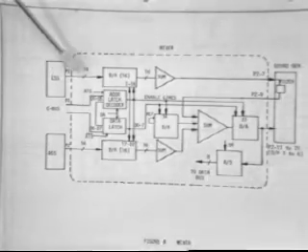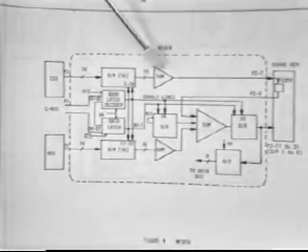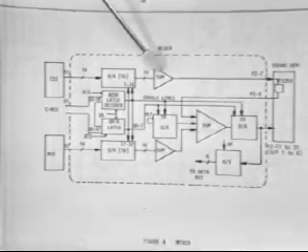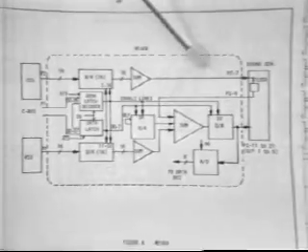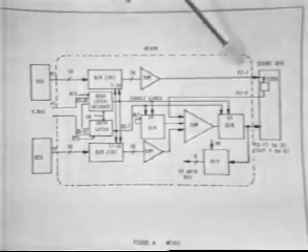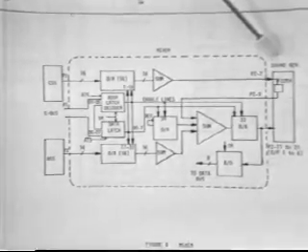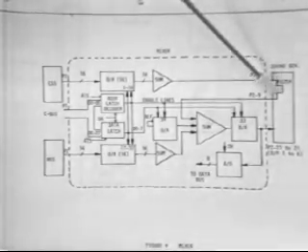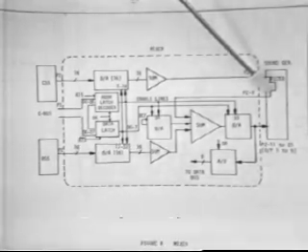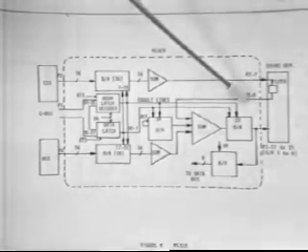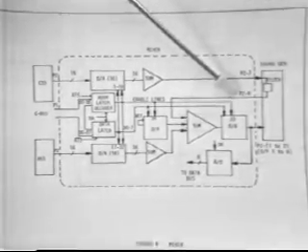Now, you'll notice that the CSS goes out through a summing amplifier where all the 12 sounds are blended together, and then sent out of P2 pin 7 into the sound generator through a filter which is completely independent of the sound generator, back into the mixer at P2 pin 9.